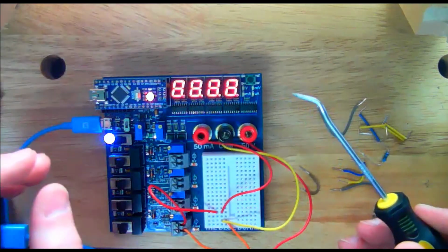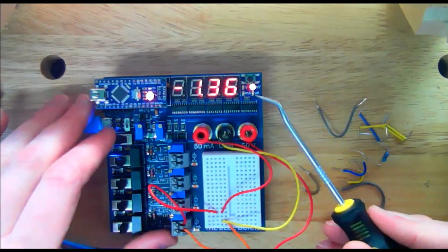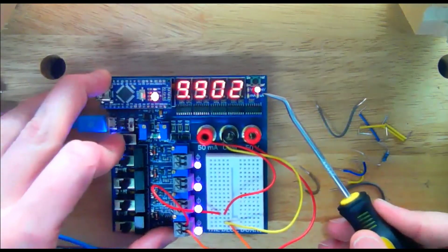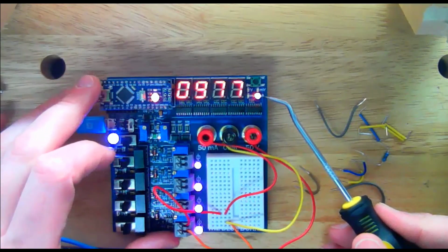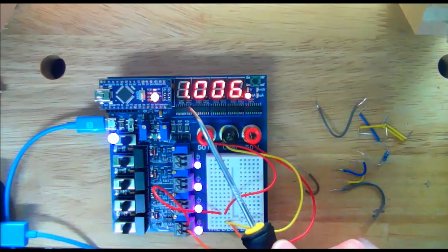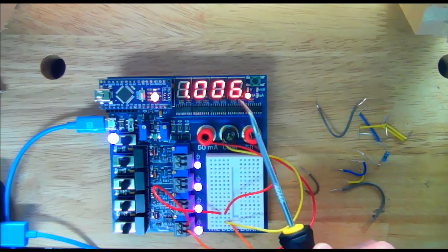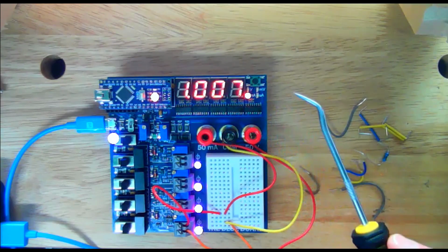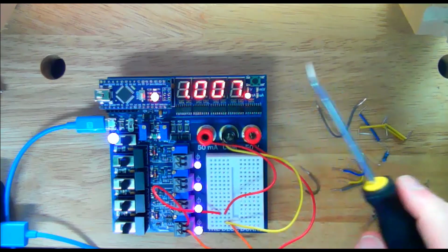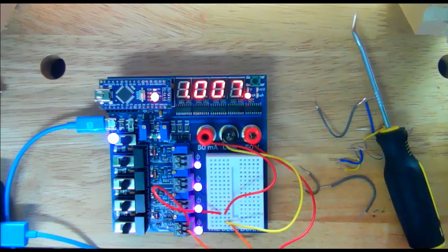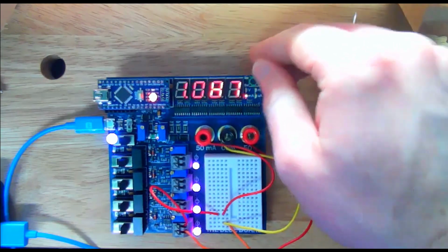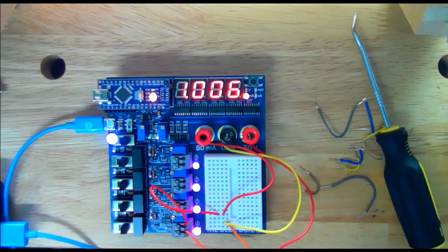Sorry, my power supply, I'm going to have to find a better power supply. Let's energize the board, and yep, it switched to microamps, and now it's switched to milliamps. 1.006 milliamps. It's a 1 milliamp current supply, so 1.006 milliamps is pretty good. 1.007, that's pretty close to 1 milliamp. We're going to have to call it good enough. We'll switch to high resolution, see if that helps. Not really, it's not that jittery. 1.006 milliamps of current. So that's our current supply that we're measuring.